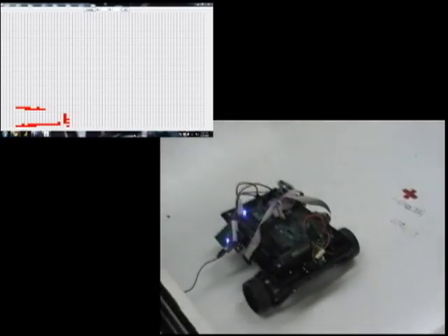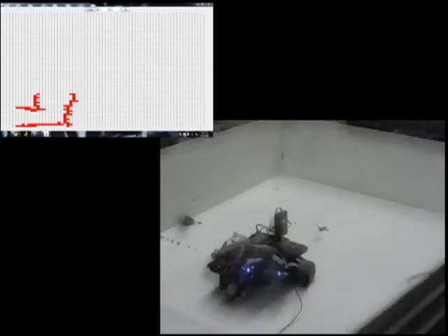And the reason the video is sped up is because the robot takes a pretty good amount of time to do sensor sweeps, which makes the overall process time consuming. You can see the robot is filling the map. It's only picking up values from less than 30 centimeters away, so we're getting a fairly accurate map, though we're not mapping too far in the future.